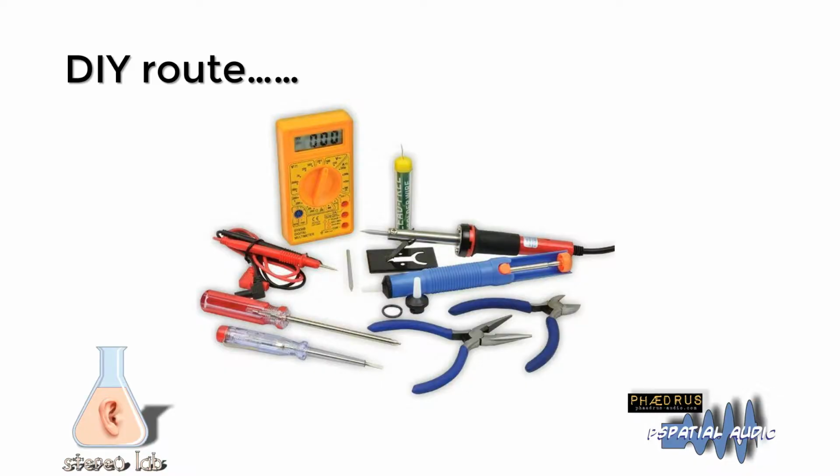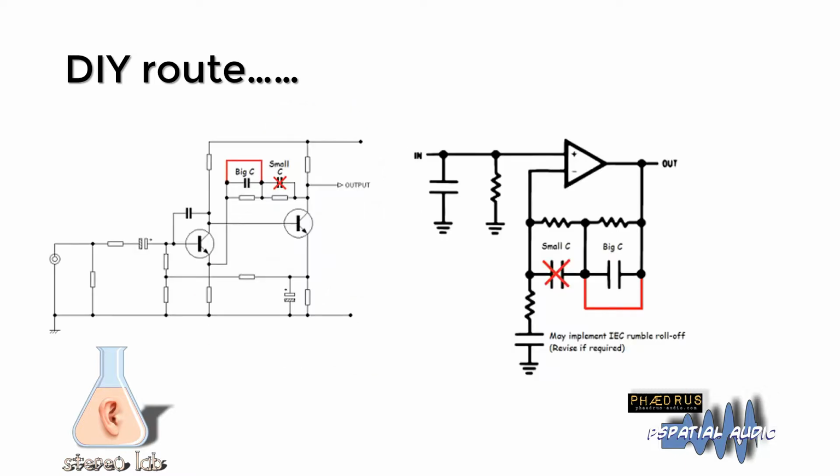Now, a commercial phono stage is a good place to start here, and you can do a number of things DIY. Normally the designer of a phono stage has looked carefully at the noise issues and all the rest of it. So it's very easy to in fact modify an RIAA stage to take out its equalisation. And models are available at all price points, obviously. And we have quite a bit of information in the help pages to explain how one would do that modification.